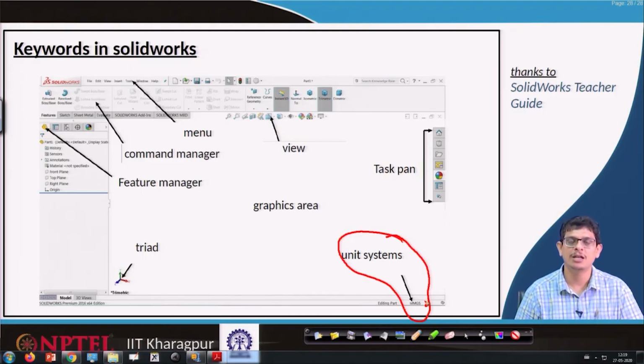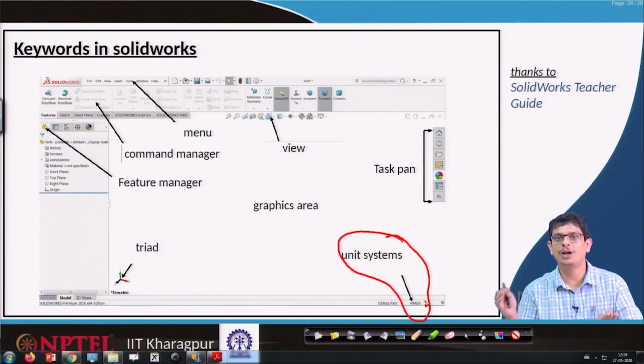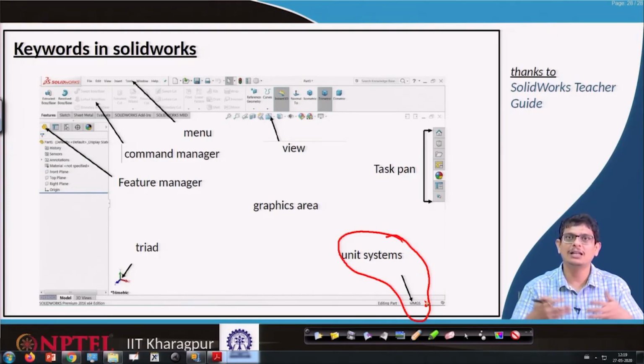But throughout your geometry, remember that you have to work on one system of units. You create some object, save it like a part drawing, then you want to make it assemble. Unless these units match, you will not be in a position to get an effective drawing. So, be consistent all the time with one kind of units.